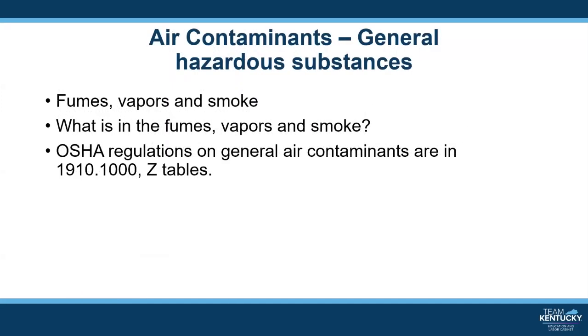Air contaminants from general welding will create moderately hazardous substances. These can be fumes, vapors, and smoke. So what's the difference? A fume is a metal that was a solid, has been heated beyond melting, and then has become an airborne particle.